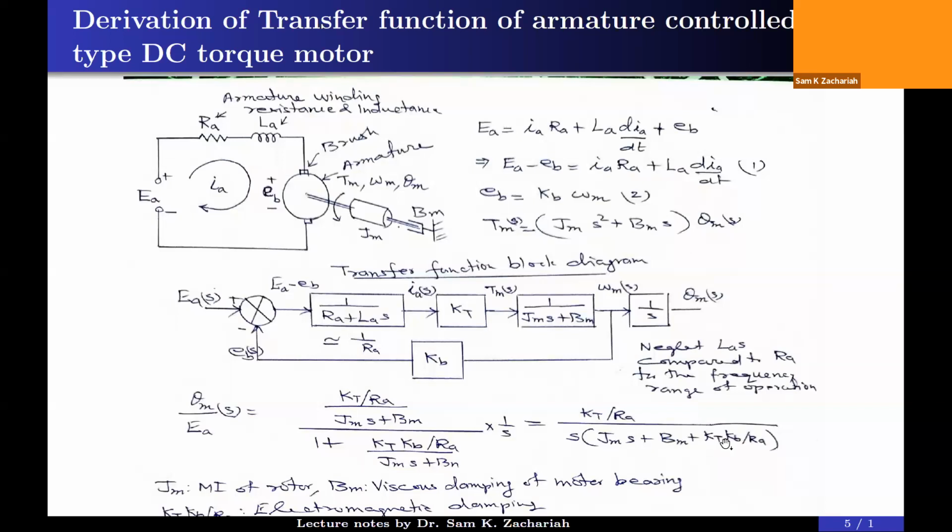But the moment you close the circuit of the armature, you need not connect any EA, just close it. Then if you try to rotate the motor by hand, you will experience, in addition to the mechanical damping, an electromagnetic induction effect. You can call it electromagnetic damping. That is the additional effort to oppose the generated currents. So this additional term is called electromagnetic damping.